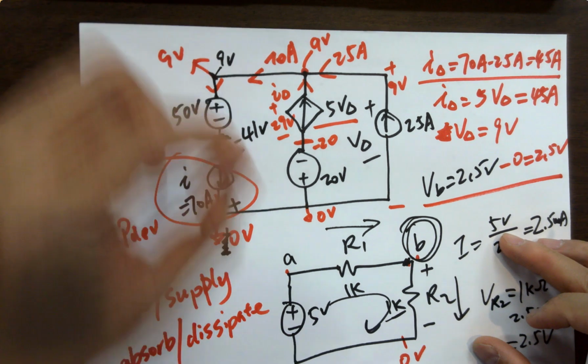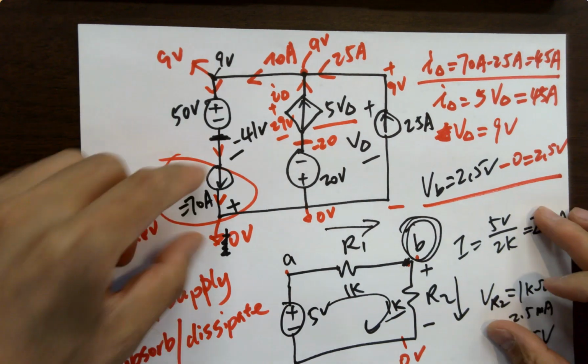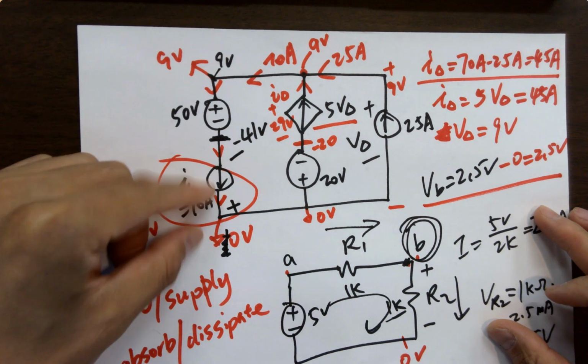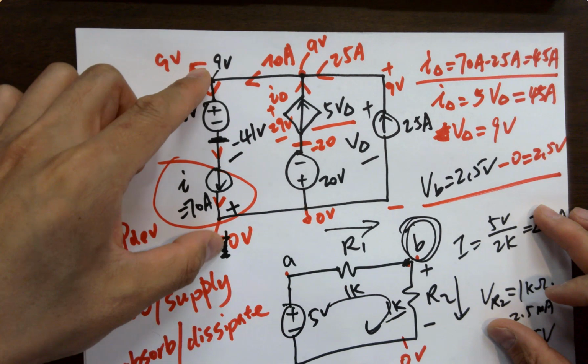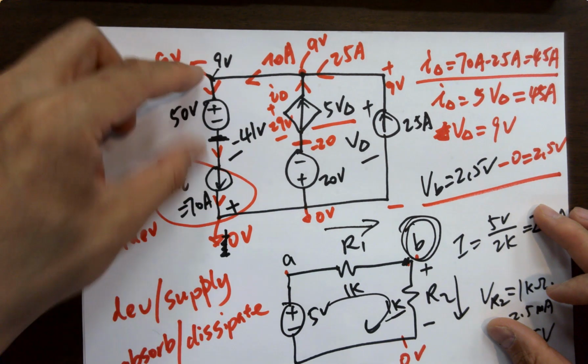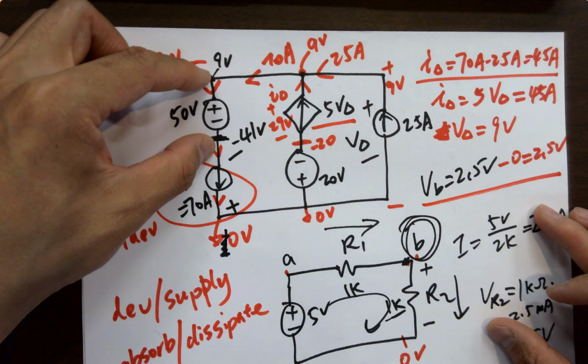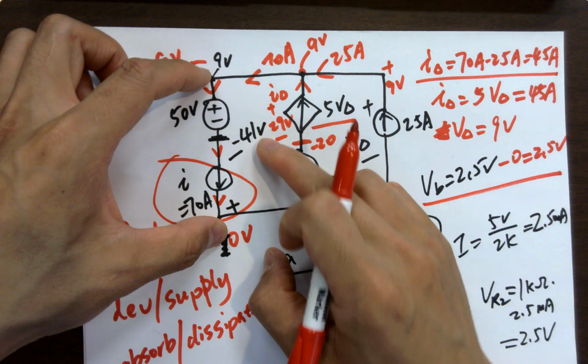That's the definition. So the battery only defines the voltage drop from anode to cathode, but not anywhere else. Right? You have one component that is boosting the voltage for a little bit. How much is being boosted? 41 volts. Right? So that's why I got 50 volts boosted by negative 41 volts. You are getting 9 volts.